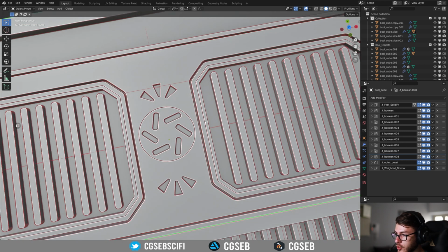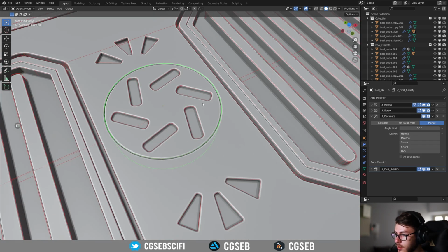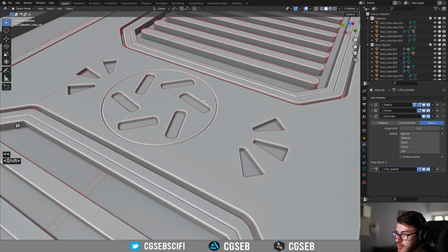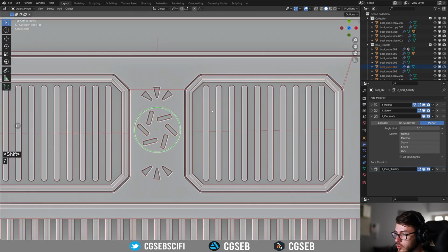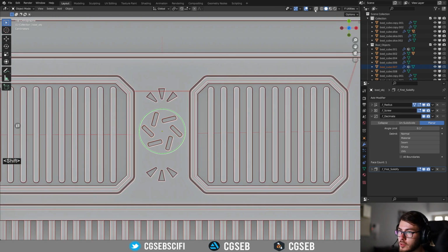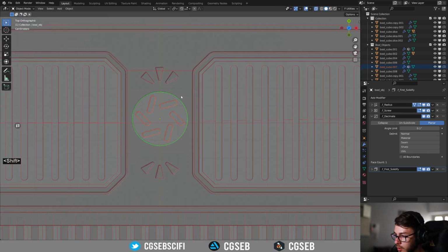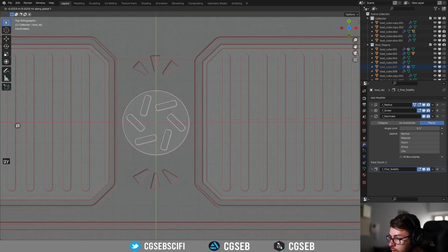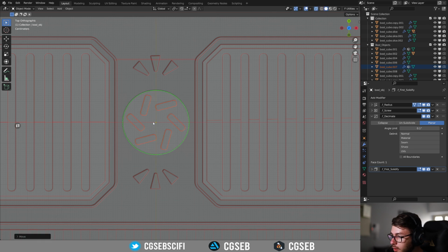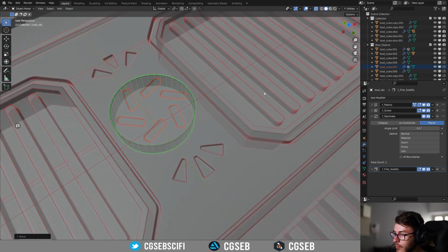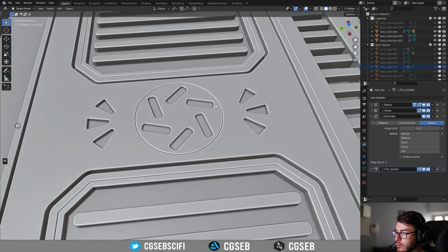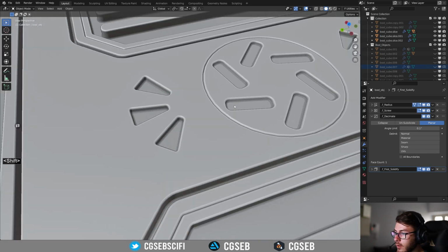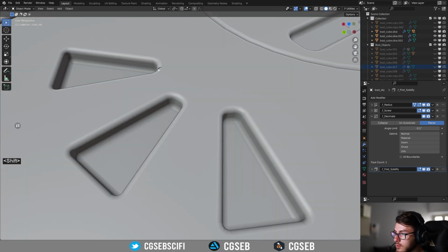So we can just right click and then if we show the booleans, select this one and this one, go to the top view and go to the X-ray mode on the top, we can actually move them a little bit here and put them perfectly in the middle over there. So that was a mistake that we did. We have an artifact over there.